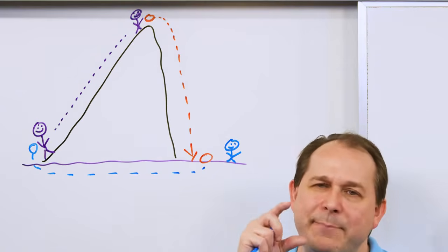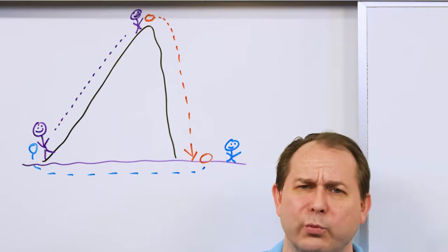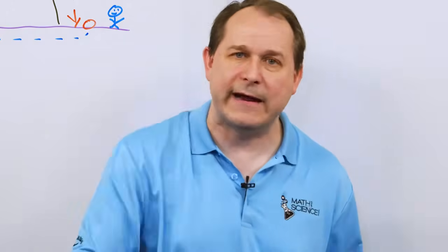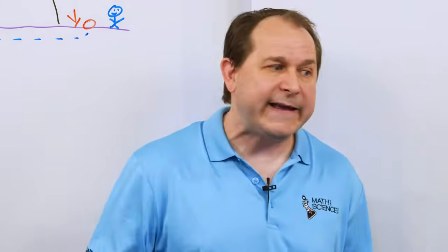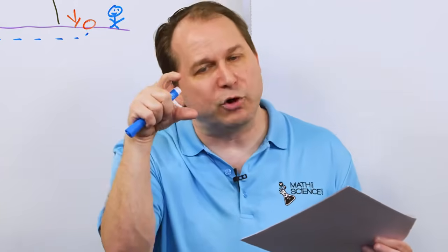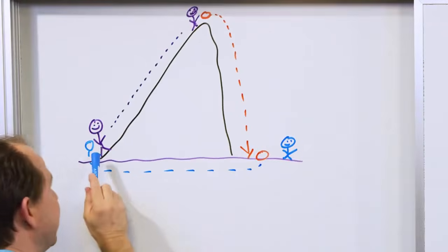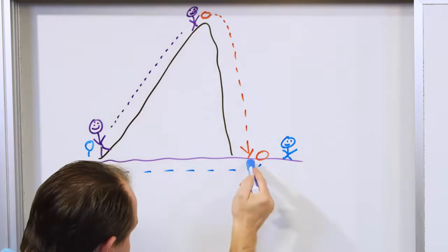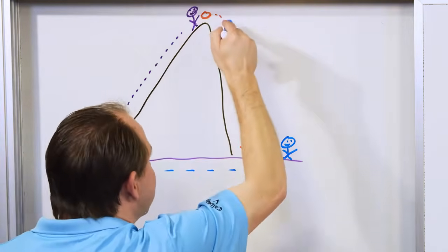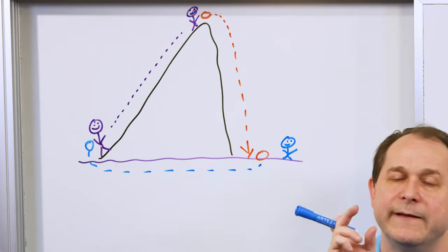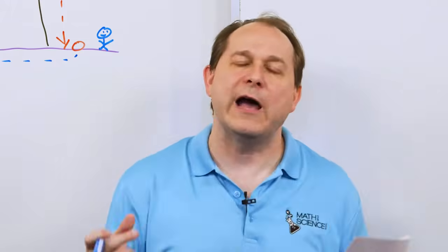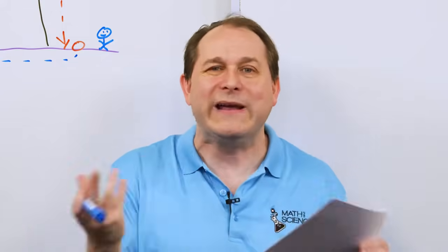You get tired. So in a battery, the same thing is happening. There's a chemical reaction that's pushing the electrons out of one terminal, and then when they go all the way through the circuit, they're kind of flowing downhill, going back down to low energy again. And then they go to the other terminal of the battery. But inside, there's a chemical reaction which takes that electron, which just came back to it, and through chemistry pumps it back up to the top. And then it goes through the circuit again, and then the chemical reaction pumps it up to the top, and then it goes through the circuit again, and so on. But eventually, the chemicals in that battery will run out. They won't be able to take the electron and shoot it out the other side anymore, because the materials have all reacted inside. And so the battery's dead, and you can't do it forever, right?